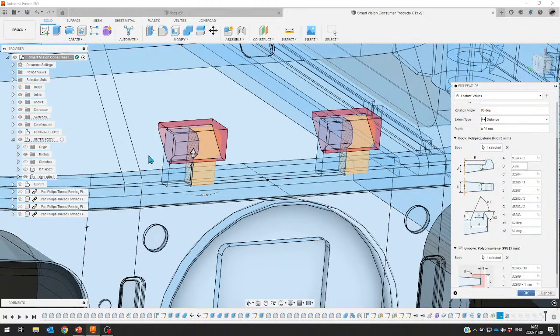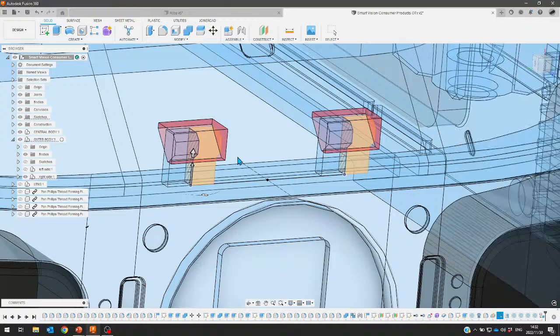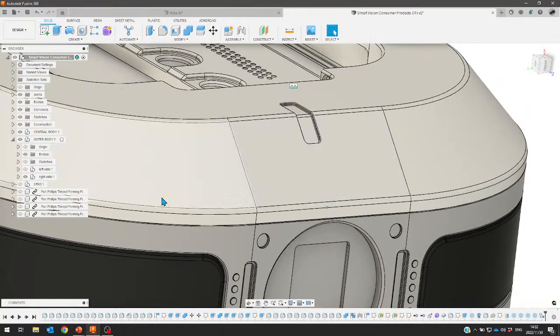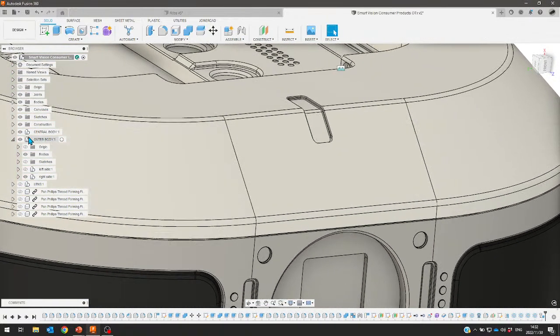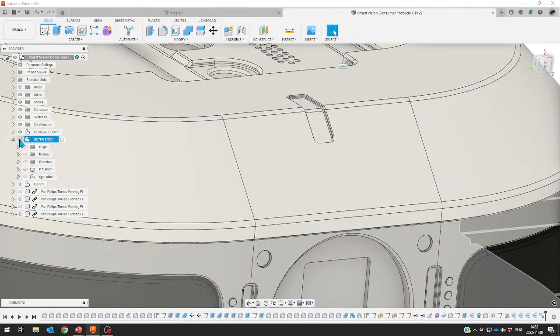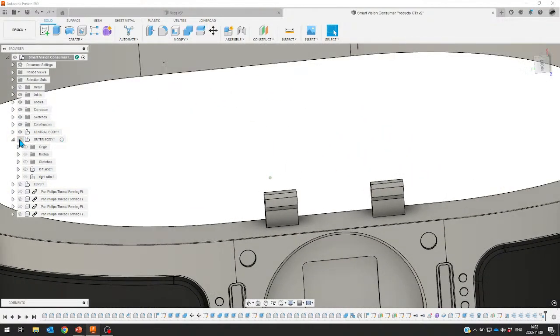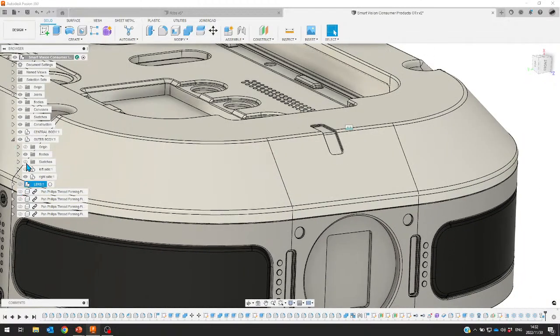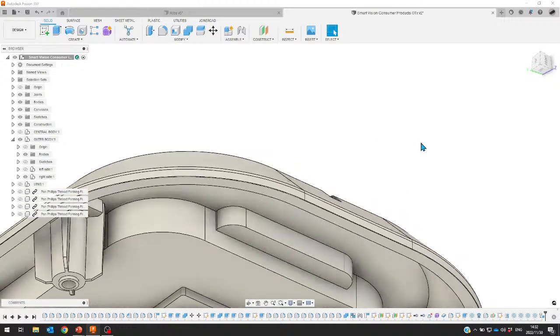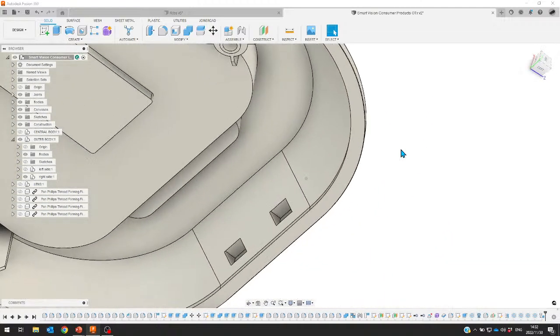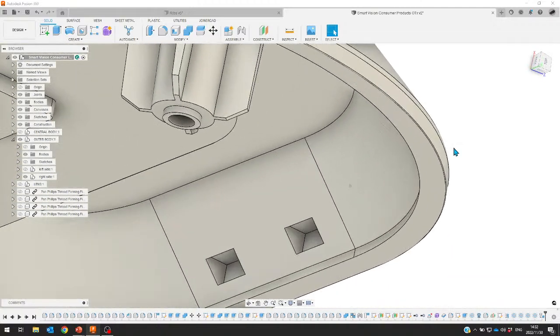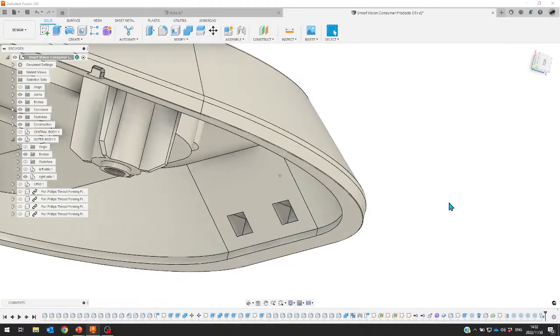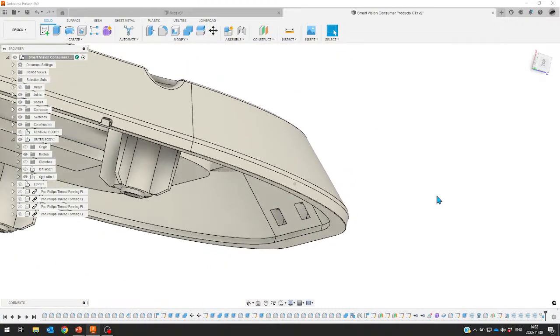That will then generate or rotate those hooks and the resulting grooves, and that will then update in our model. So if I go ahead here now and hide the outer body geometry, we can see the hooks there on the inner body. And if we go around the other way, rotate this, we can see the grooves there within that outer shell for the hooks to hook into.